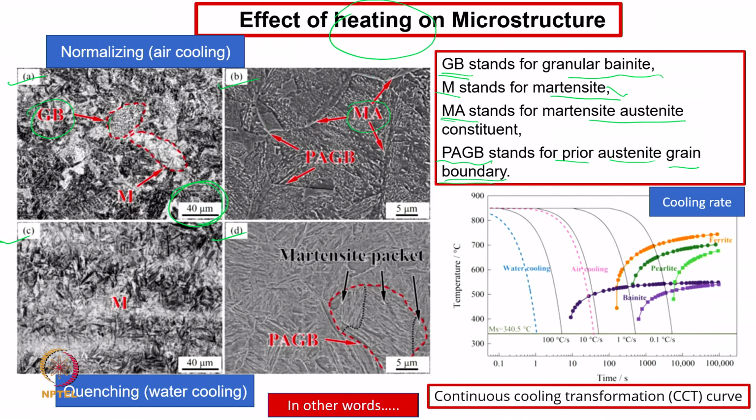So, these are the grain boundaries and maybe some discontinuities in a material, and they indicate what the constituents are, whether the martensite is going to dominate. If martensite dominates, then naturally the brittleness will increase. However, if the bainite content or matrix increases, then the ductility will increase. So, that is what has been shown.